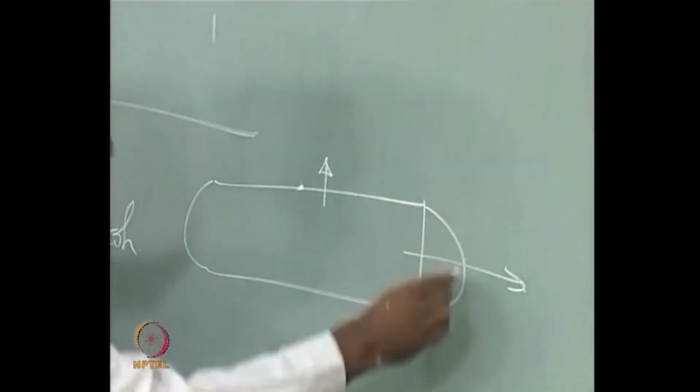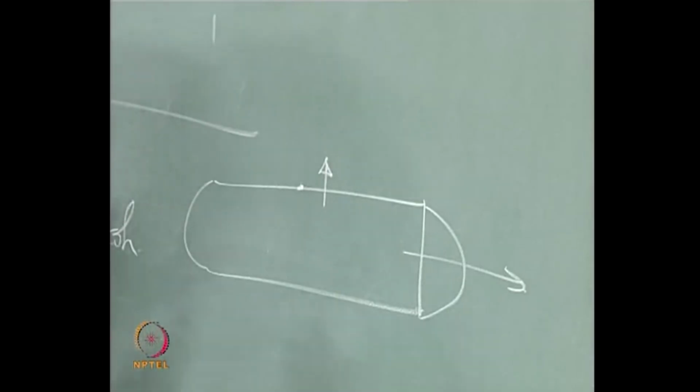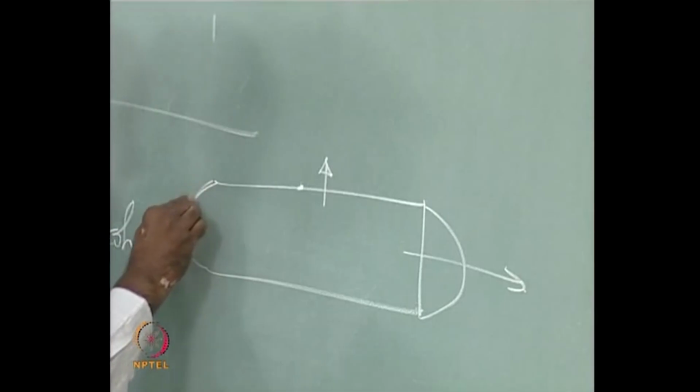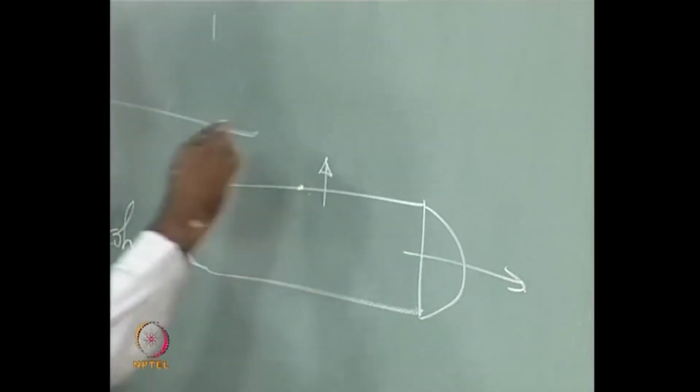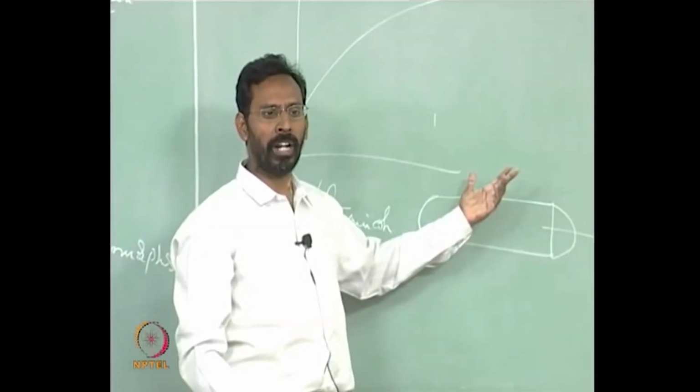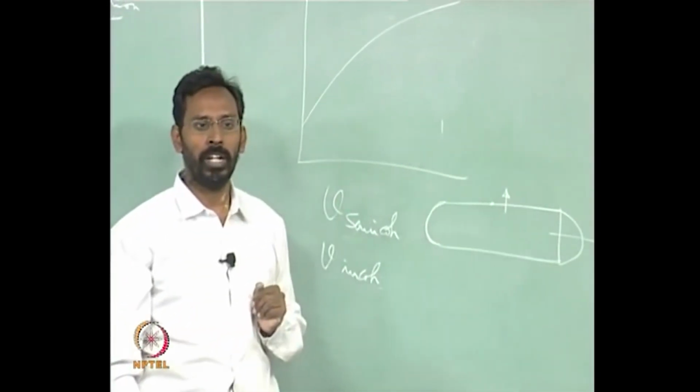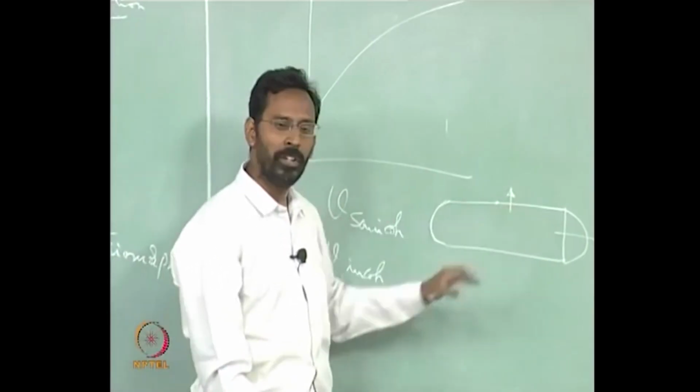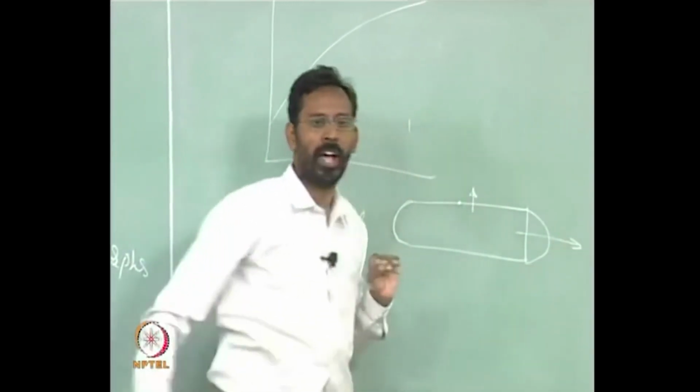There is no such coherency on these sides, and because there is no coherency on these sides, any of the plate like precipitate will always have an incoherent component plus either a coherent or a semi coherent. Initially it could be coherent, slowly it may lead up to semi coherent, and finally you would see that this whole thing grows as a plate.